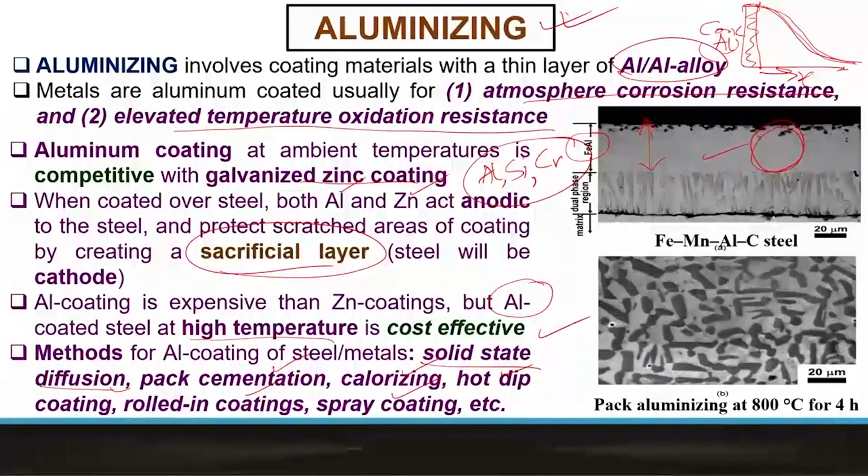This region will have all the aluminides, and below that we'll have solid solution and aluminides both present. From the top it will look like this, where these aluminides are essentially faceted phases. In other words, they are not polygonal with curved boundaries, but appear as phases with sharp, flat interfaces, which is reflective of the fact that these are intermetallic phases with high interfacial energy.